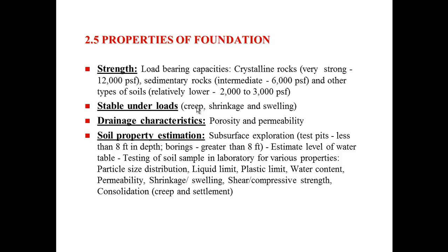Drainage characteristics, making sure that water can drain off the soils. It's not just to keep water from penetrating the foundation, but if you've got a lot of water in your building site and it freezes and thaws a lot, you're going to end up with some problems with your foundation, especially if it's not down below frost level.